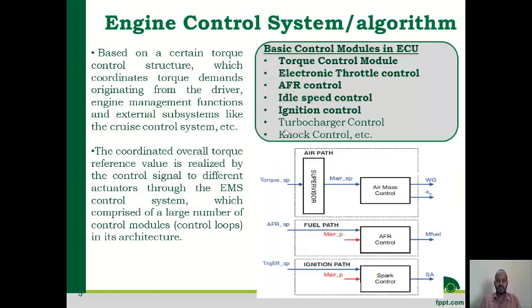Now, the engine control system algorithm. How is the control algorithm inside the engine control system, or engine management system, designed, and what are the parts of the internal control algorithm? About this internal control algorithm, I have already given a lecture on the SI engine control system architecture, so for more detail please go through it. Here I will touch upon the basic control modules present inside the EMS, like the torque control module, electronic throttle control module, air fuel ratio control module, idle speed, ignition, and turbocharger.